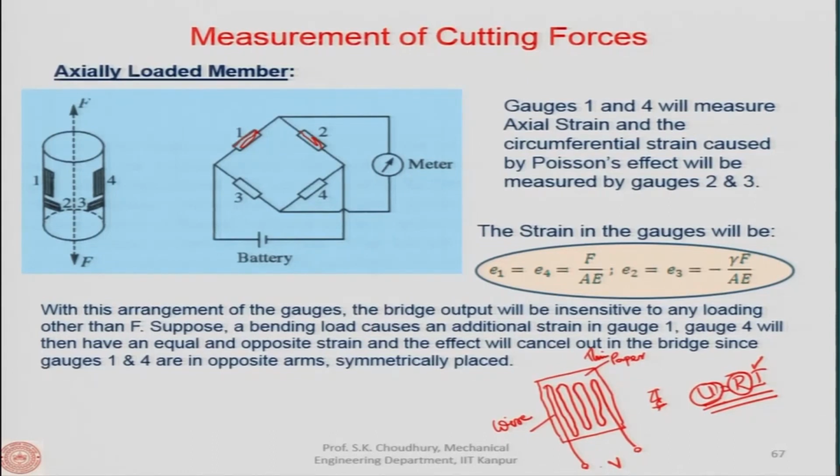Any small deformation should be sensed as a change in the resistance in this wire. But if it is torn anywhere, you will not be able to find out, because the wire is glued to the paper and the entire paper is glued to the member. So it is very difficult to find out if anything is damaged in the wire of the strain gauge.